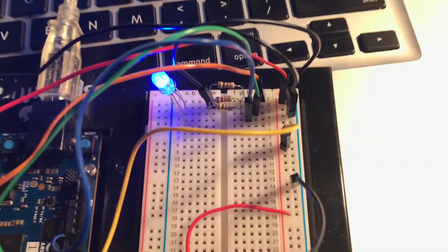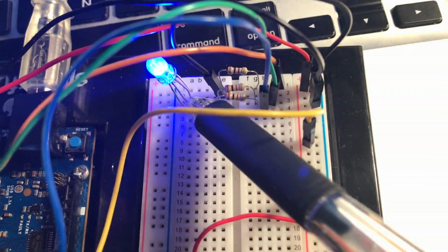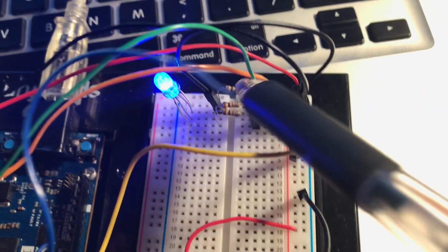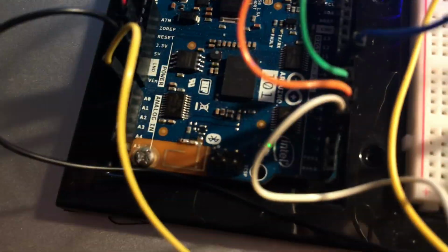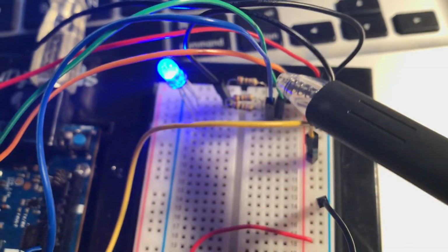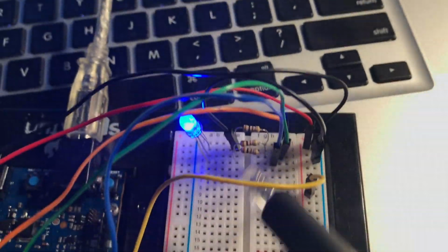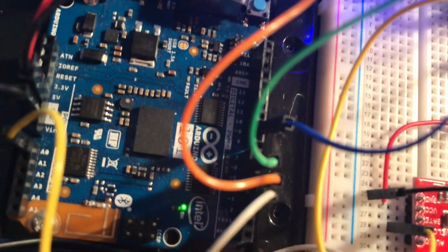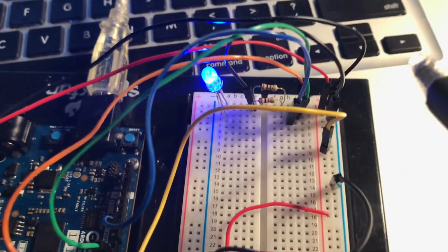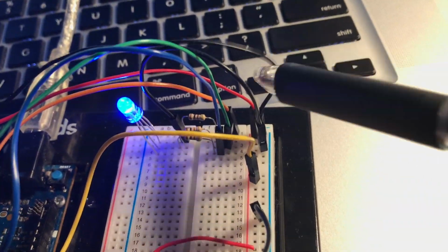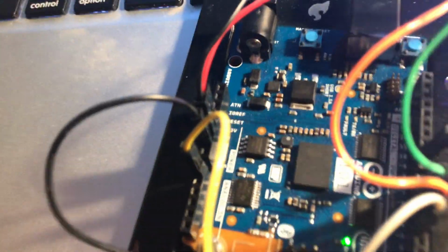Then we get up to the RGB LED, the red pin, and then the green pin and the blue pin go through these 100 ohm resistors and are connected by these wires. So the red pin goes to the orange wire here into pin number 5. The green pin is connected by this green wire here to the digital output pin of pin number 6. And then the blue pin is connected by this blue wire to digital output pin of 9. And the RGB LED is grounded by this black wire here into the negative column, same as the board, through this other black wire into the ground pin on the Arduino board.